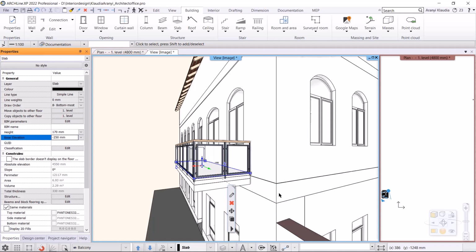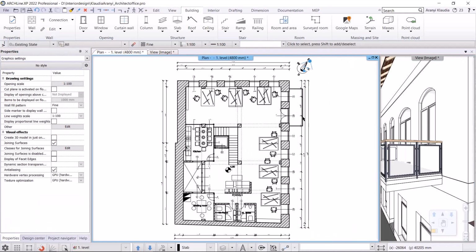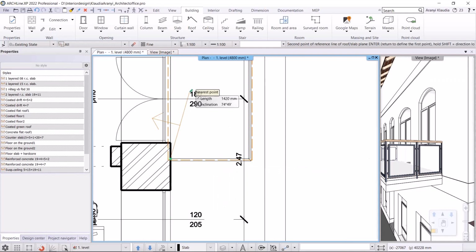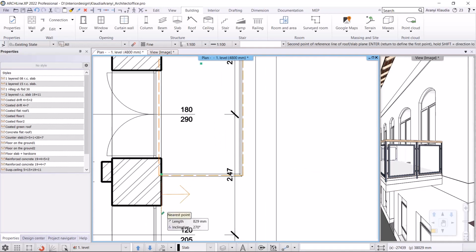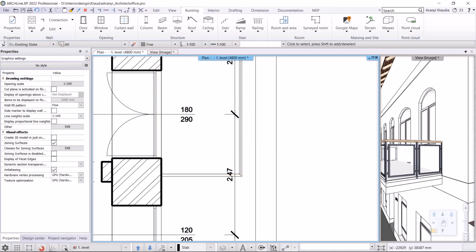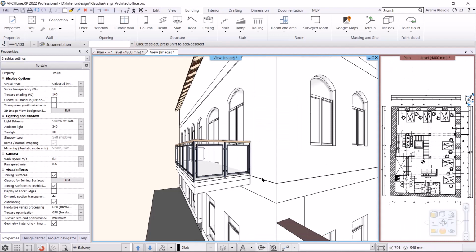The next thing to adjust is the slope of the slab. This can be set afterwards. Select the slab and choose Modify Inclination by reference line from the local menu. You have to specify which side of the slab should be sloped, and the angle value. The direction of the slope depends on whether you enter a positive or negative value. Here I give -2 degrees. You can see that the entire slab slopes outwards. My goal is to have only the sloped concrete layer variable thickness, so that's what I'm going to set now.